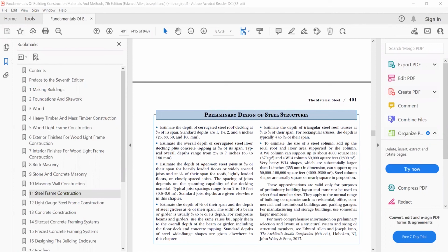Different buildings have different structural requirements. A library, for example, like the example I showed you, has quite a heavy load that you need to design for. Books are very heavy. And so, some of the criteria that we're looking at in this preliminary design table may not apply to certain structures. But we'll just go with the basic rule of thumb of a W8 being an adequate column size for the project.